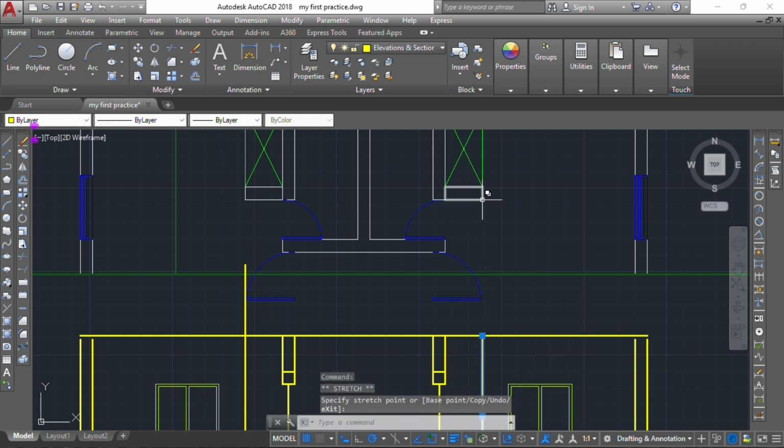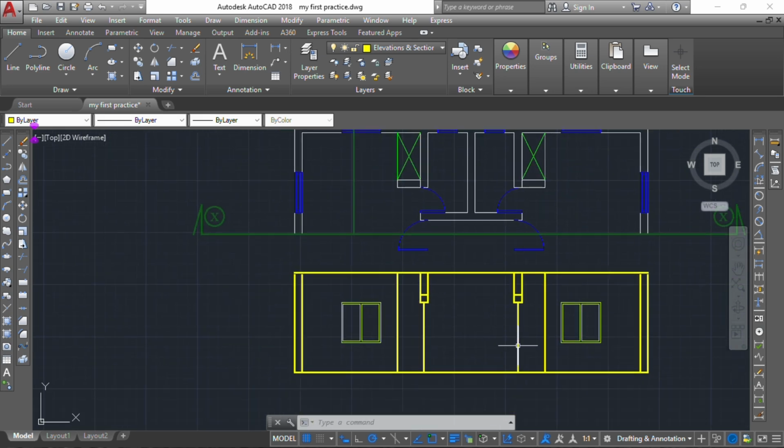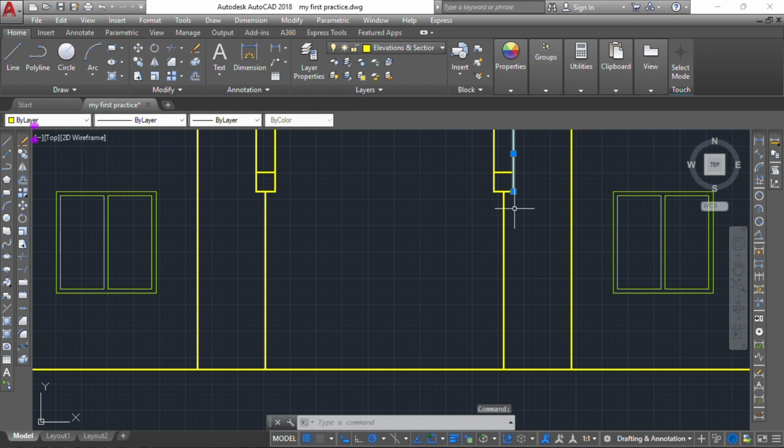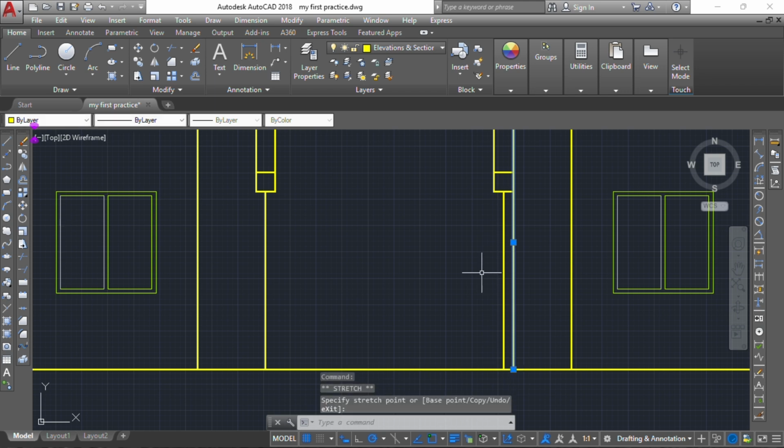Okay, so now we can go ahead and adjust this closet wall also, which is this single line, this edge here you are seeing, right? You can just go ahead and edit that also. And then I think if we are standing here, we'll be seeing this wall edge also, this edge here and this edge. Should we indicate that? Okay, I think it's advisable to indicate it, because sectioning deals with anything you are seeing. Anything after cutting the plane, anything you see, you have to draw it out, right?